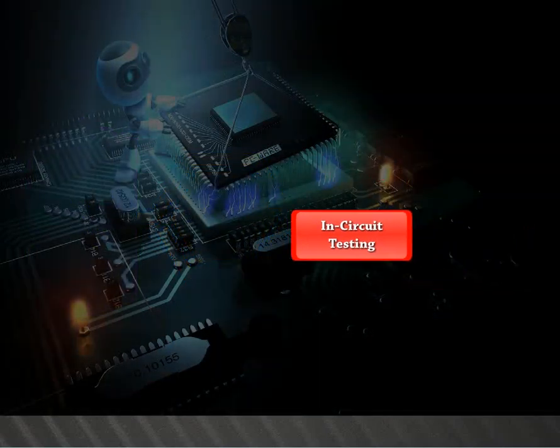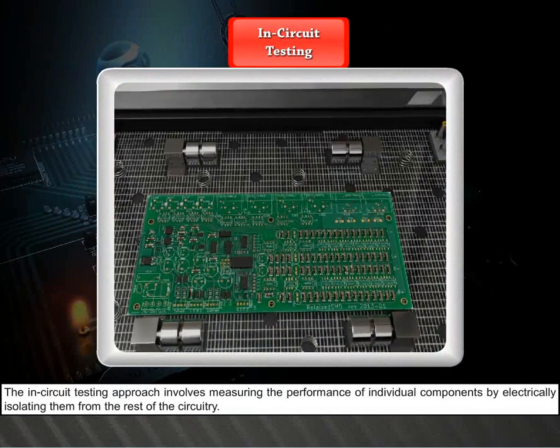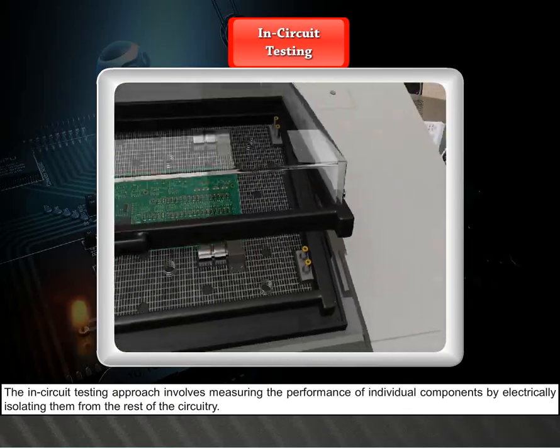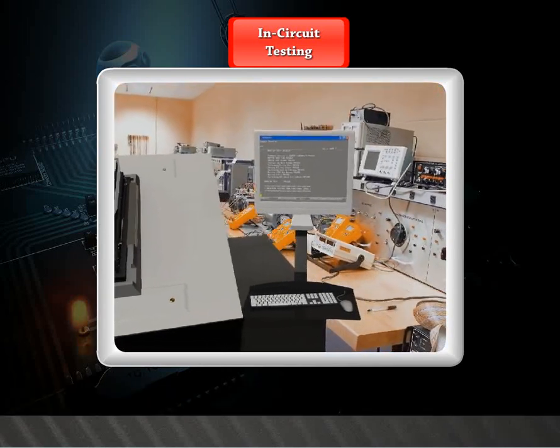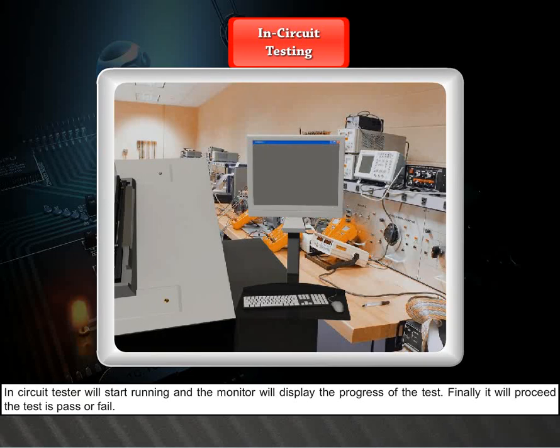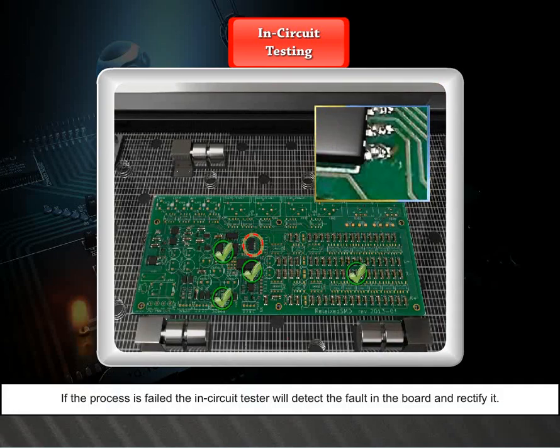In-circuit testing. The in-circuit testing approach involves measuring the performance of individual components by electrically isolating them from the rest of the circuitry. The in-circuit tester will start running and the monitor will display the progress of the test. Finally, it will show whether the test is pass or fail. If the test fails, the in-circuit tester will detect the fault in the board and rectify it.